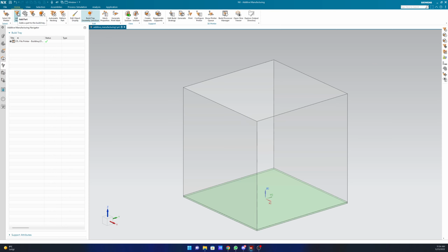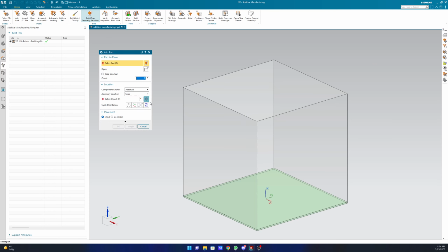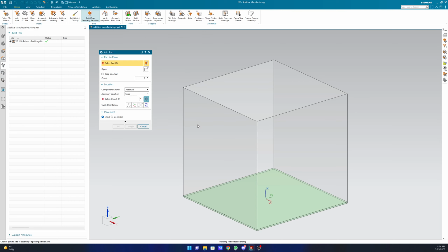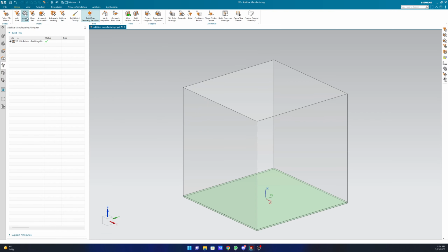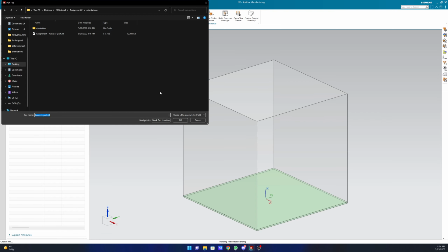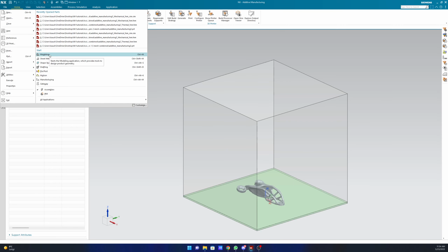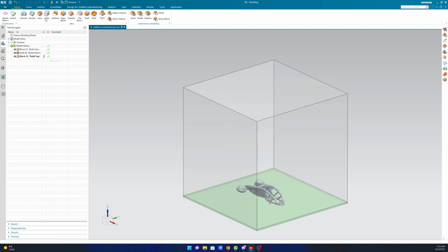Now we'll add the part. So we go to the folder, search for, oh, we need to do import STL file. Go here, temp, this is our file, click on OK. So basically you just keep it there. Then you go to file and modeling. In modeling, then you go to design for additive manufacturing and then click on part orientation.